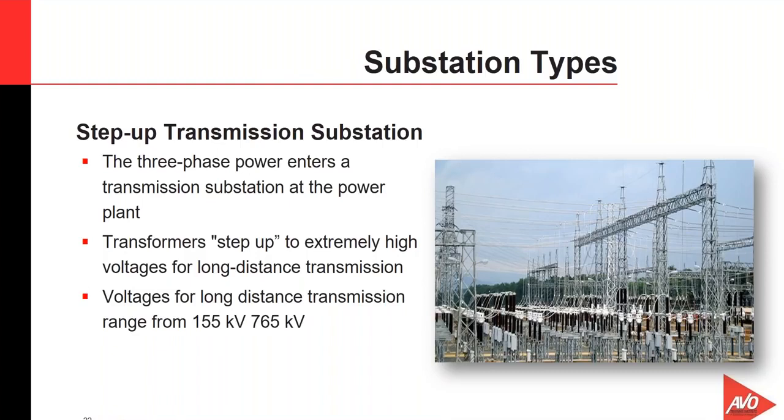Okay, so step-up transmission substations. Let's start out with that. A step-up transmission substation is generally going to receive power from a power generating facility and uses large power transformers to increase that voltage for transmission to way far off locations. There can also be a tap on the incoming power feed from the generation plant to provide electric power to operate equipment inside of that generation plant.